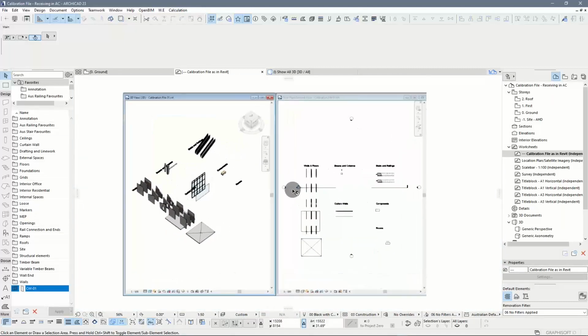You want to make sure that you understand what it is that you're going to receive. And again, the whole purpose of this will be a handover. So we have asked the Revit side to exchange with us an IFC model in schema 4, that is IFC4, with the model view definition, or MVD, for design transfer.